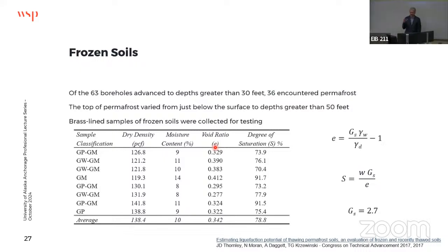What I didn't talk about here is this really sensitive time. I talked more about long-term. We have load restrictions in the springtime, right? And we have load restrictions because the soils are really soft. And so like Farmer's Loop, where you have this silt especially, that's really soft material. I didn't talk about that in-between time where you're even more susceptible, even soils that we might not consider totally liquefiable by really simple definitions would potentially cause us pretty big havoc as they're really young in their period of thaw.